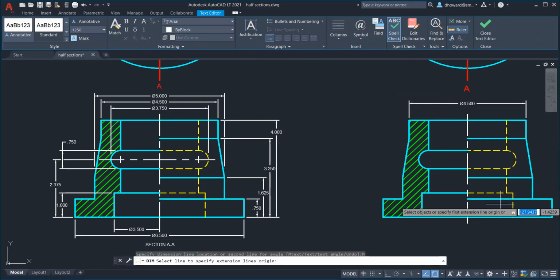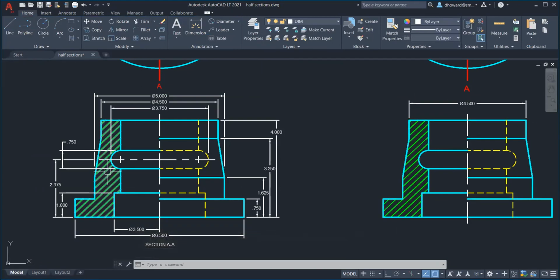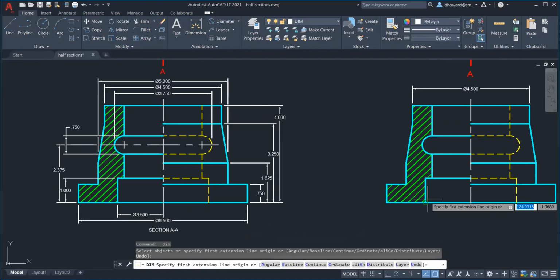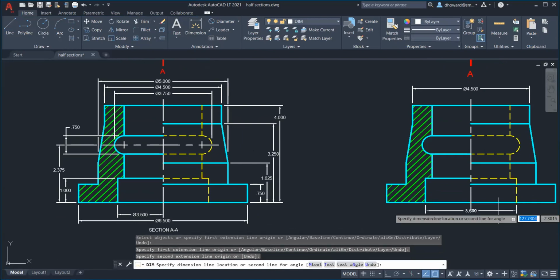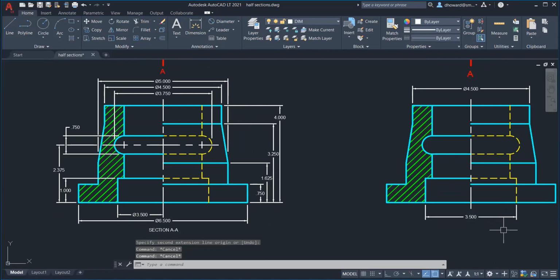And now I can place the dimension with the diameter symbol. Another thing to point out that I did over here, a couple things. This dimension here, now this is an interesting situation, this 3.5 inch. The truth is, ideally, we would be able to dimension this hole like that right there, from edge to edge. That is the hole in question, a recess. But the problem is we're not allowed to dimension to a hidden line.